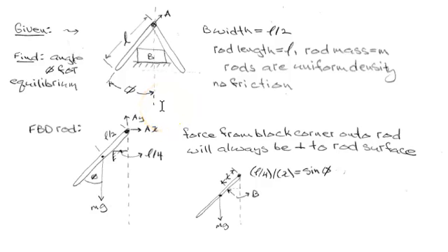So using that, we can start assembling some free body diagrams and relating weight to angle and keeping everything in equilibrium. And this time, again, we're going to need multiple free body diagrams, and we're going to end up, I believe, drawing a free body diagram of the pin, which is going to be an important consideration we'll use later on for frames and trusses. So we'll start with the rod on the right. It's symmetric, on the left. We could have started with any of them, and not surprisingly, this is a bit of a geometry chase, but it's good practice.